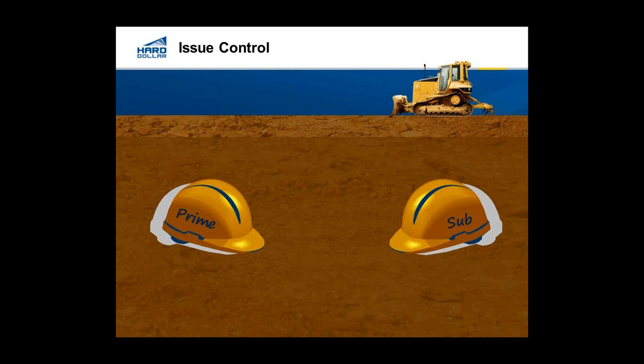In this case, the excavation work is broken into two activities. The first activity is some stripping. Now that's just the first 6 inches, and you can see it's at $2 per square yard. And then the other portion is excavation work, or general excavation. Notice it's at $10 per cubic yard, and if you did the math there, you find the excavation is more pricey because they're actually going to be doing some fine-grade subgrading in there.